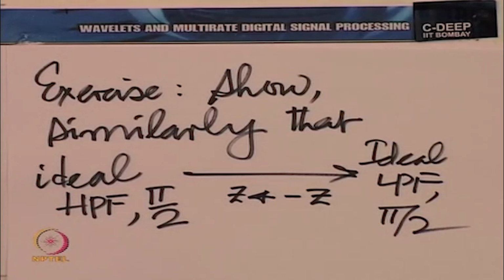And that also makes a lot of sense for the other of the two requirements for alias cancellation. So, today we have looked at the condition for alias cancellation and we have interpreted the simplest of the conditions. Now, if you do not stick to the simple condition and if you have the factor of R z, all that we need to do is to say that we are also modifying that filter a little beyond just this low pass to high pass and high pass to low pass conversion. That R z factor would carry out that modification.